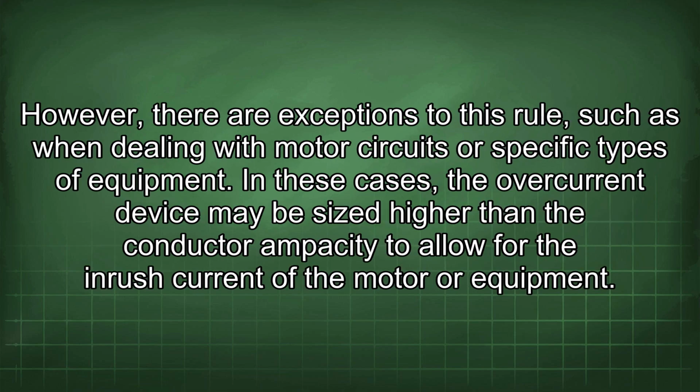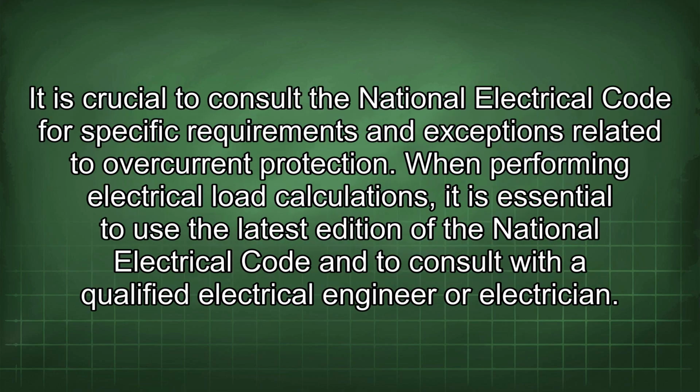However, there are exceptions to this rule, such as when dealing with motor circuits or specific types of equipment. In these cases, the overcurrent device may be sized higher than the conductor ampacity to allow for the inrush current of the motor or equipment. It is crucial to consult the National Electrical Code for specific requirements and exceptions related to overcurrent protection.